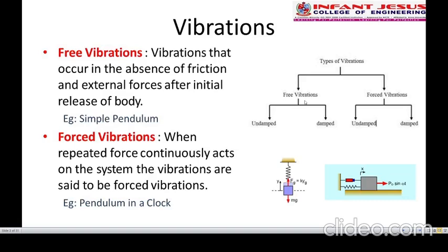Free vibrations are when the periodic motion continues after the cause of the original disturbance is removed. When we give some disturbance to a body, when we pull the body, and then remove the force, there will be periodic motion in the body.